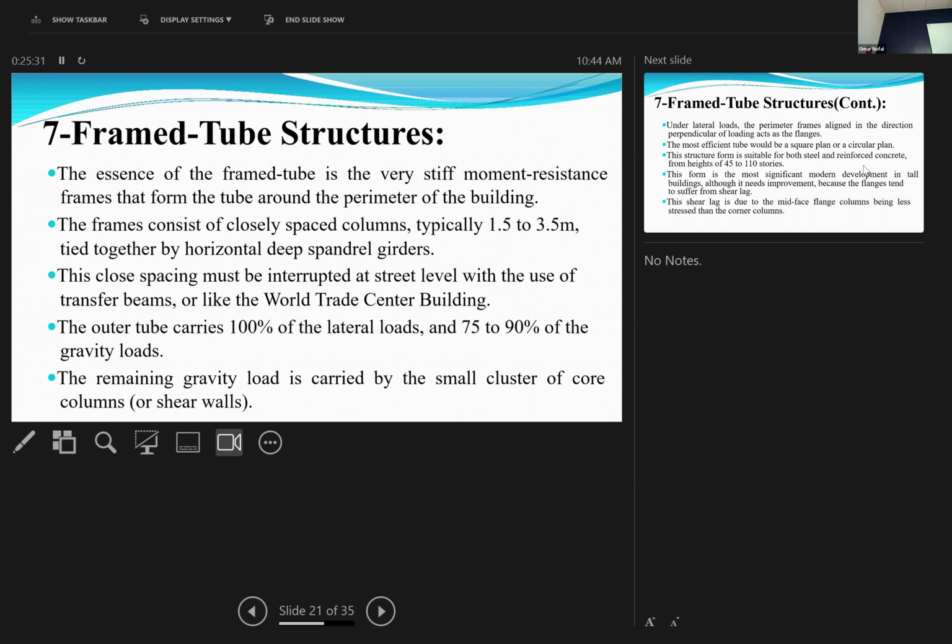But if the beam that connects these columns is very stiff, like the story height, like this beam depth, let's say it's 1 meter. Yeah, it's good. If it's 2 meters, it's much better. What if it's the story height? So that's actually a shear wall, right? So this beam is going to move as one piece. But if it's not stiff enough, it's going to have a little bit of deflection. So that's actually what happens. So it pulls this column, so you are losing this.